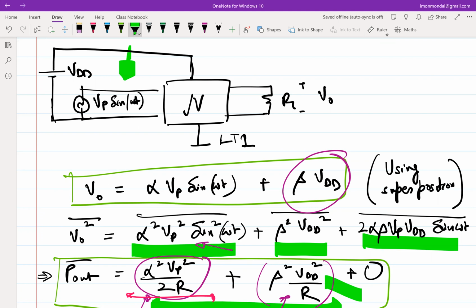So essentially an LTI system allowed me to use superposition, and that's what I could get, right? So even though the total observed power can be as high as you want by cranking VDD higher and higher, you won't get that power at the frequency that you are looking for. Make sense? So essentially, even if you have a battery, even if you have n number of batteries, an LTI system cannot give you power amplification at the desired frequency.